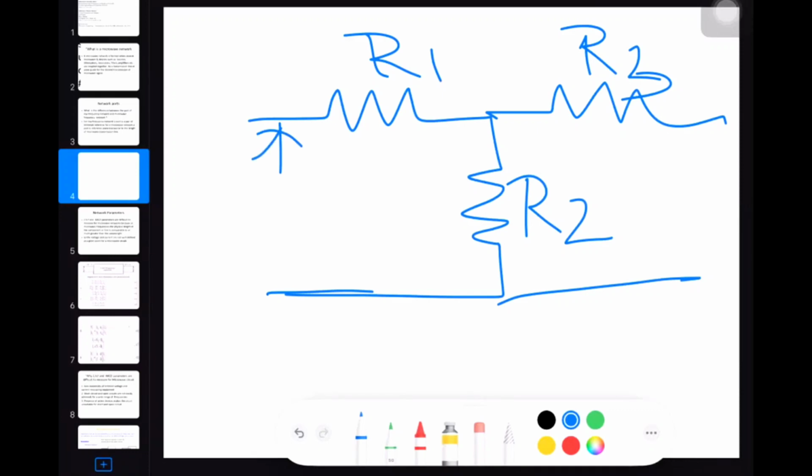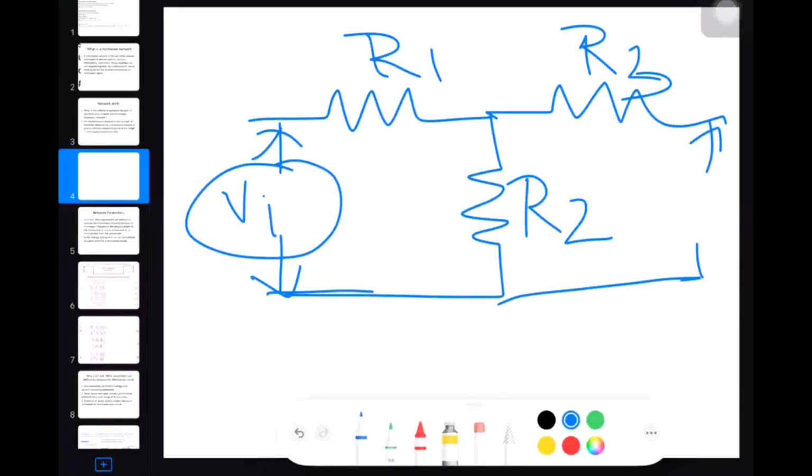If I want to analyze the circuit, we use the concept of H parameters, Z parameters, Y parameters. Here I consider the circuit to be a low frequency circuit. In a low frequency circuit, whenever the circuit has to work, we give a voltage called the input voltage, and the voltage obtained across the output is called V naught, the output voltage. We may measure the output voltage directly, or connect a load resistor RL and observe the output voltage.